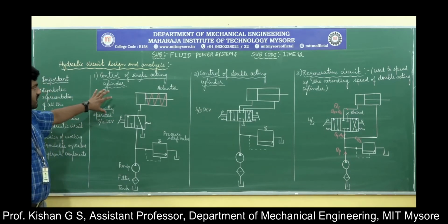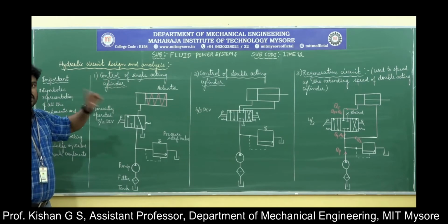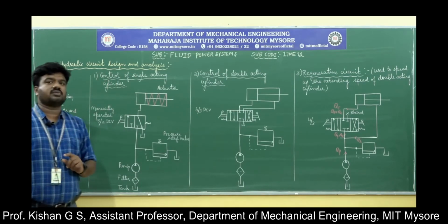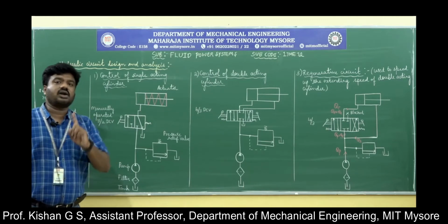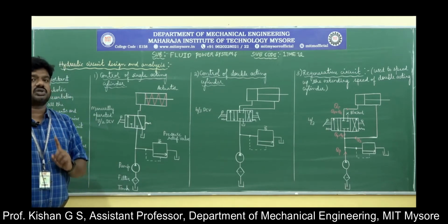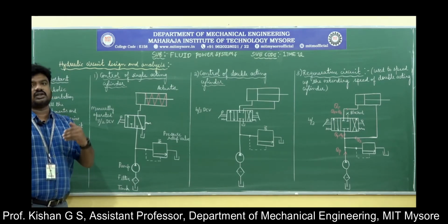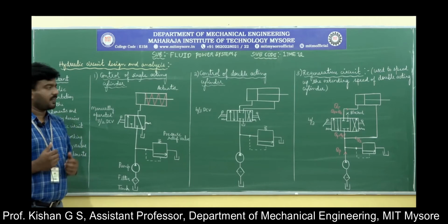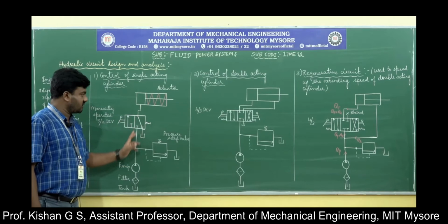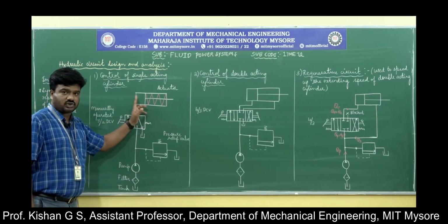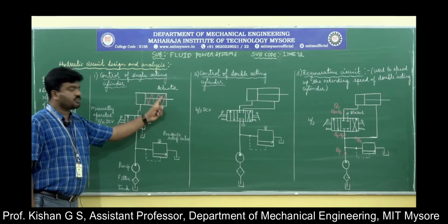Okay, so you can observe here the major purpose is to control the single acting cylinder. Remember one thing: when we use the term single acting cylinder, there will always be control of one action of the movement of the actuator using the pressurized fluid. Basically it is the extension, or carrying the load. Here in the actuator, we are going to have the supply of fluid on one particular side so that the extension is achieved. Regarding the retraction, it is spring assisted.